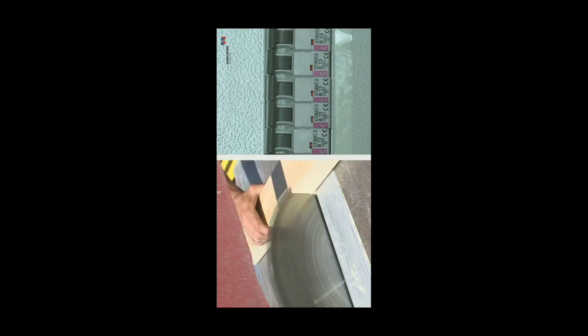Miniature circuit breakers, or MCBs, are installed in residential and non-residential buildings or are used for industrial applications. In order to allow for typical appliance inrush currents, the MCB must remain stable during a minor short-term overload. However, if the overload persists, the MCB must open the circuit after a certain period of time. During a short circuit, an MCB must interrupt the current safely in order to minimize damage. MCB tripping characteristics show a thermal trigger for overloads and a magnetic trigger for short circuits.